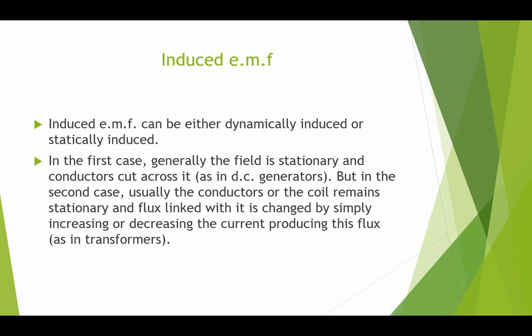In statically induced EMF, the conductor or the coil remains stationary and the flux linked with it is changed with the help of the current producing this flux. So this is the difference between dynamically induced and statically induced EMF.